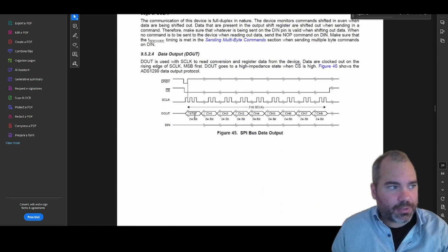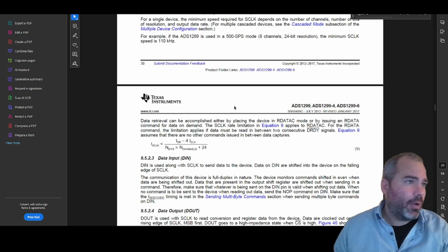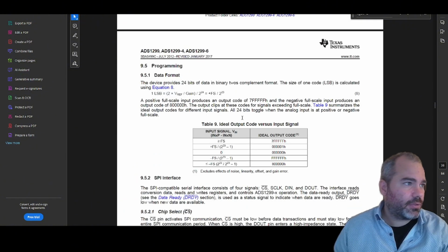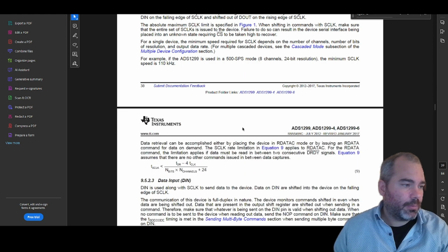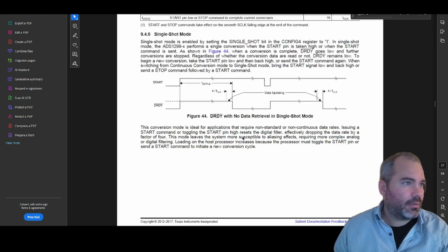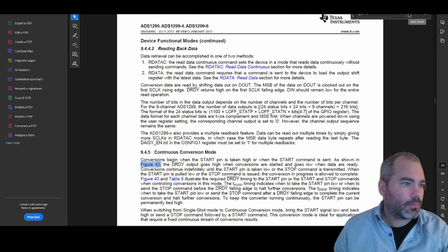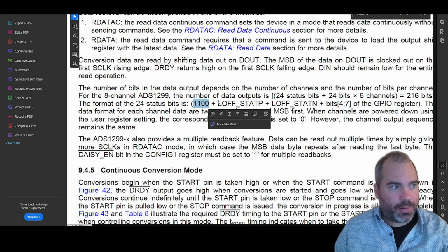Okay, the first one is the status bit, status 3 bytes. And what happens is that because it's sending the transmit first, sorry about that, data in, data out, where is it? Here, we end up missing these 4 bits plus the first 4 of this register.